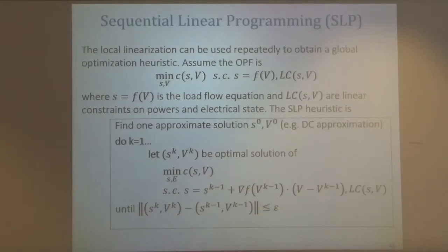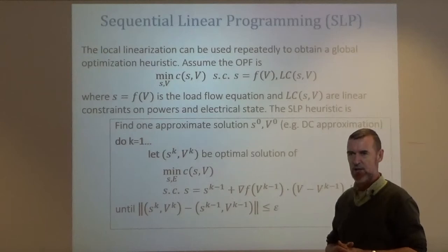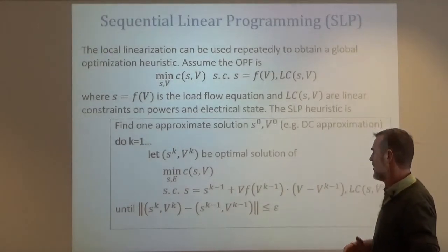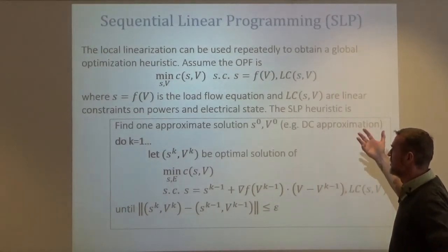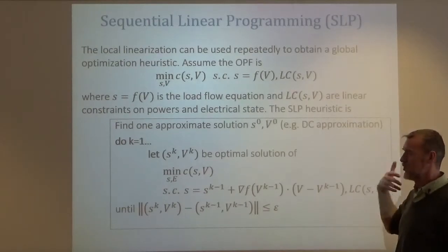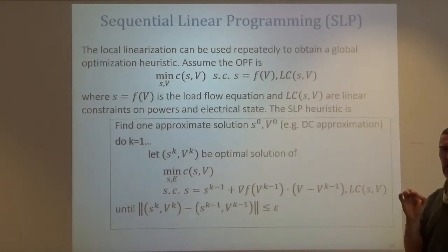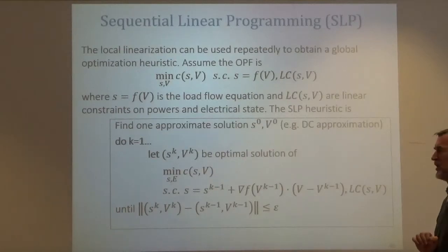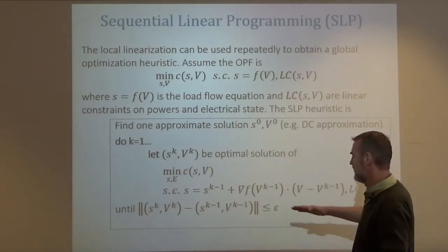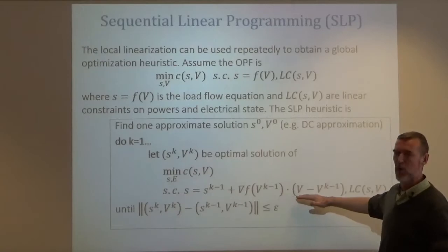This is a simple case. We can use that iteratively, where this has a name. The idea is very simple. If I want to solve an optimization problem, what I can do is find an initial guess, linearize all the power flow constraints around this value using the Jacobian matrix we've said before. Once I have done this, I'm writing that in a very compact form.